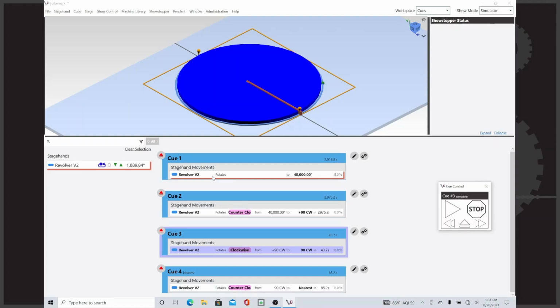And so the idea, I guess we kind of skipped over the elevator pitch, but the idea with a dynamic spike is that with a regular spike, you explicitly define the value for it, but in a dynamic spike, it's calculated. The value is calculated at runtime based on the current position of the motor and other coefficients that you enter. It will dynamically change based on the position of the motor when the cue is loaded. And that's pretty sick, because then you can do crazy stuff like run an entire turntable show with just one cue. Just one cue, without changing anything.